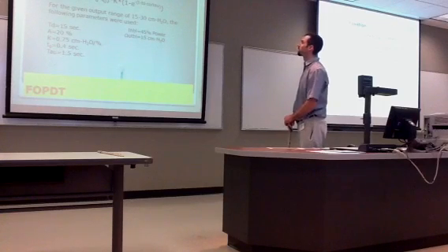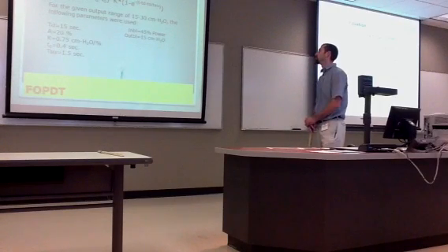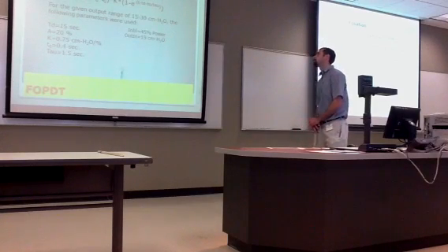This modeling equation is C(t) equals A times u(t minus TE minus T naught) times K times 1 minus e raised to the negative of (t minus TE minus T naught) divided by tau.